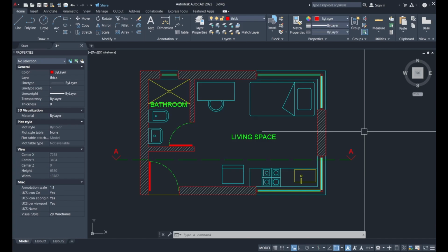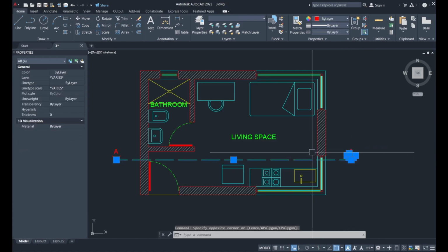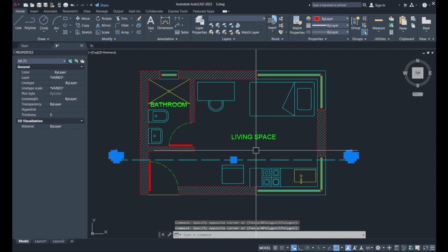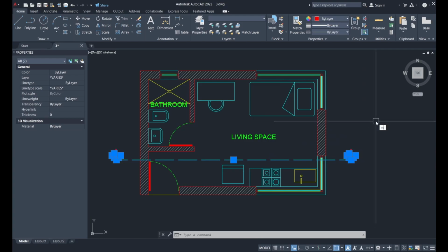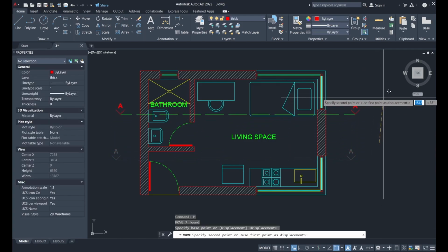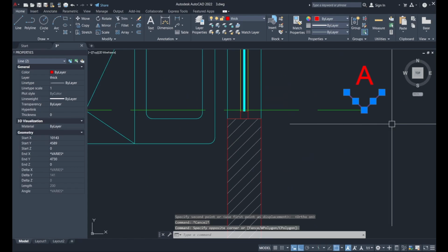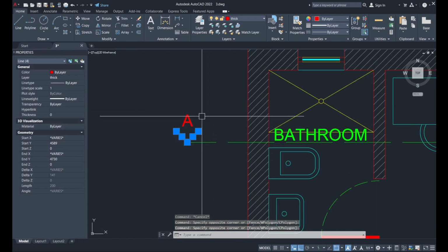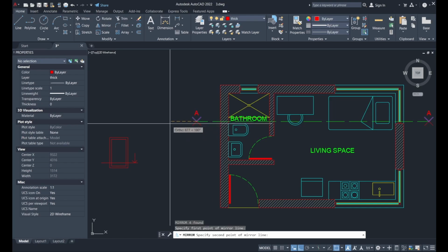We ended the last video drawing the section line. Now, for ease of drawing, I'm going to change the position and direction of the section line. I've realized to draw this plan better, I can just move this section line over to this window, and I'm just going to mirror this using MI.